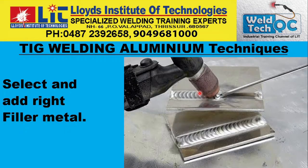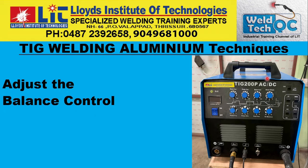And obviously you need to select the right filler metal. The filler metal specification has been given earlier. You can refer to those. So you have to select the right filler metal to match the base metal. And as necessary, you ensure to adjust the balance control, that is the cleaning action as well as the penetration.